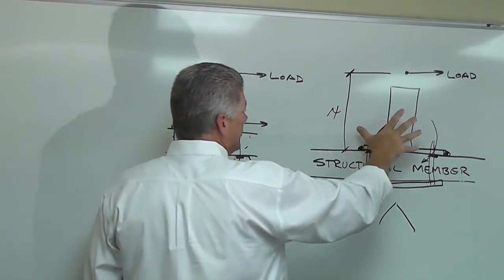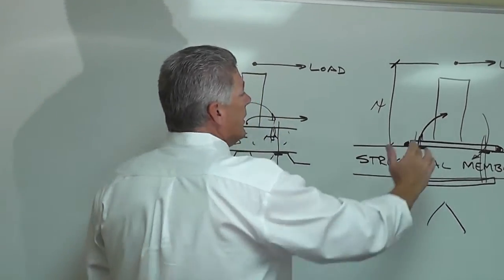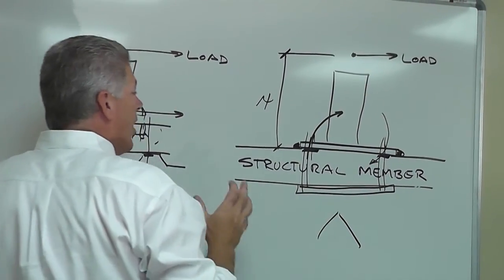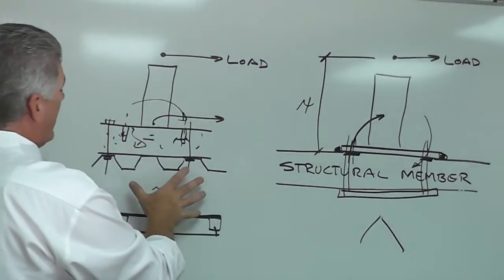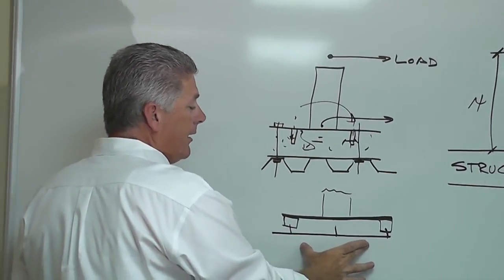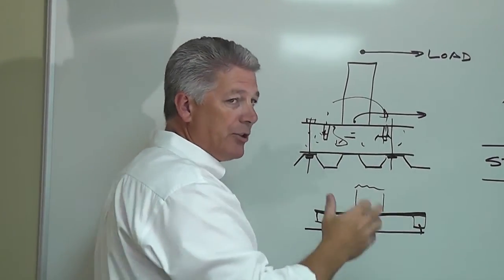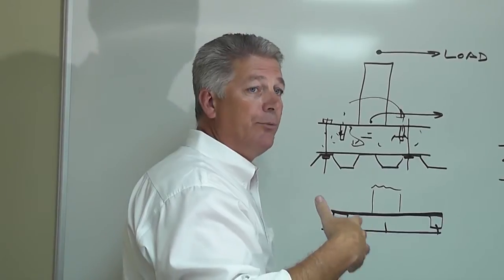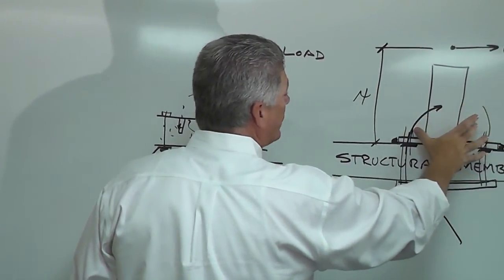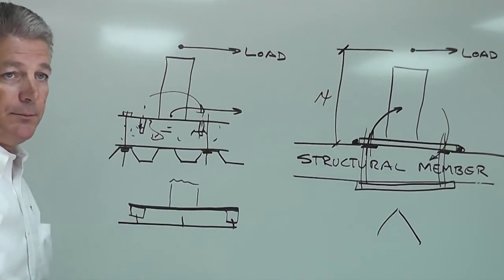Where the advantage of a rigid post is that the post itself can vary in height. It's also used in applications where a metal deck, let's say that this is a standard trapezoidal type metal deck, the integrity of the deck does not allow us to attach to it because the deck itself is not going to absorb the load. We would go to a rigid post design, and a lot of times we can vary the height of the post based on the application.